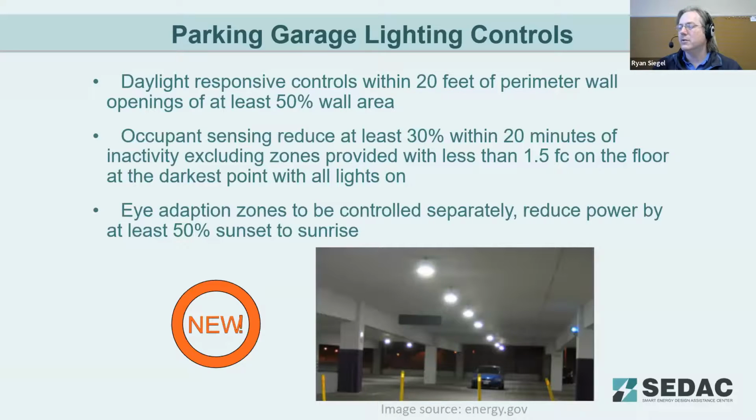Do you have a question here regarding that daylit zone and the width of it? That again is kind of called out. So where that daylight is, that whole width, it will depend. So if you do have a building where the entire side is 3 foot tall glazing, then your daylit zone is going to be that 3 foot coming in the entire width of the building.